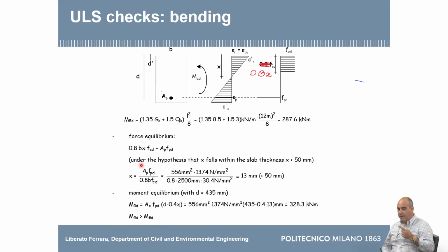But what we have to bear in mind is that this safety check is still satisfied with a good margin. Also because never forget that we already have 1.4 and 1.15 in the materials. And we also have 1.35 and 1.5 here. So if you factor 1.4 average with about 1.2 average from the material, 1.4 times 1.2, it's already 1.7, something like that.